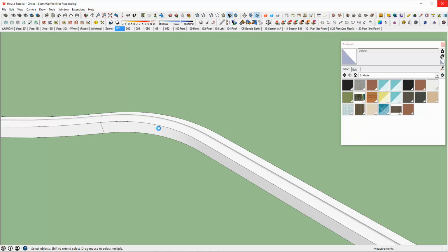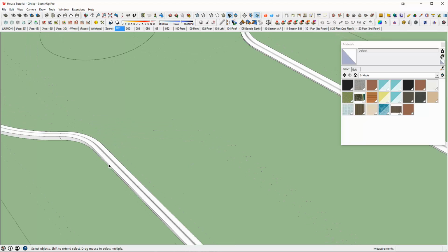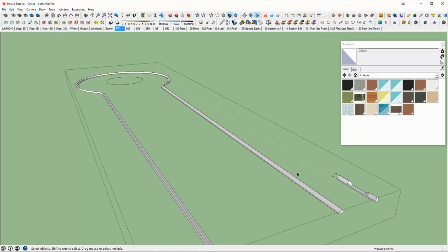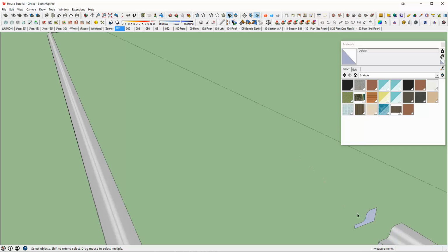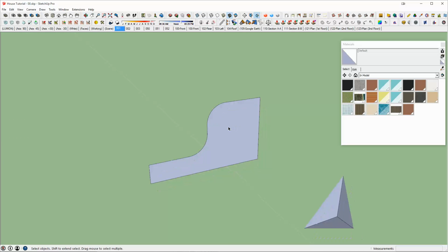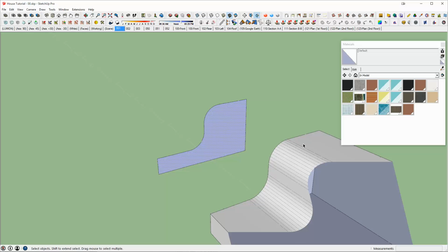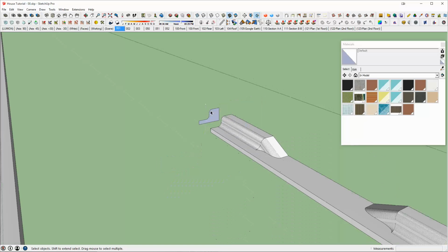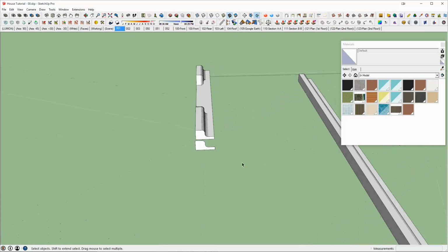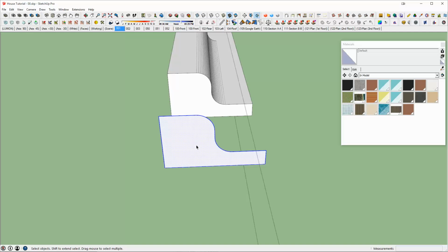This actually is slowing down the machine just a little bit, and I'm going to show you why in one second. So the reason why it started slowing down, and I can show you real quick, is we've talked previously about the level of arcs and how many segments they have, and this one seems to have quite a bit. And so I'm actually going to redraw this and reduce the number of segments that the arc actually has.